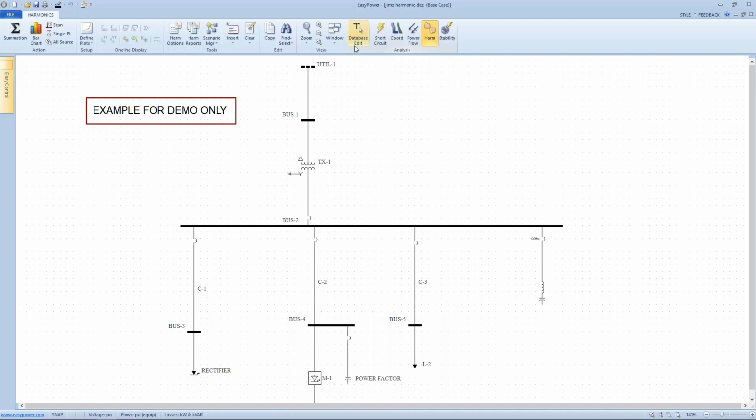So if I go to the harmonic module, which is this icon here with the different waveforms, I want to look at the summation of harmonic distribution. I'm showing on my voltage distribution, VTHD is at 56%, and I'm seeing 13% on my total current harmonic distribution, and 110% again with this capacitor in place.